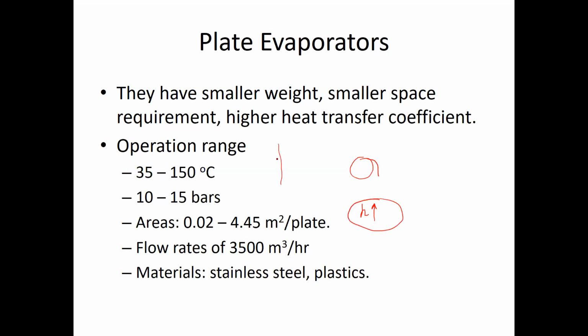This is not the same with vertical tubes, where the boundary layer forms and increases in thickness so that the value of H drops as you are moving down. And accordingly, the H value for the vertical tube is less compared to the average H for the horizontal tube. Did I answer your question? Yeah. Do you mean the boundary of the water? Yes, the salty water forms vapor, a boundary layer over the surface, and the thickness increases.